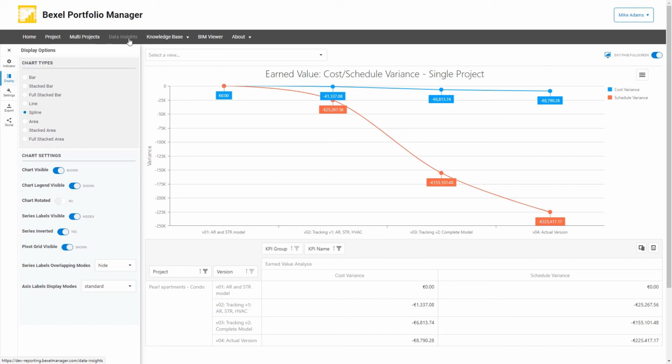The platform will also have additional links and connections with knowledge bases where users can access and use various analysis templates such as IDS templates for automated BIM checks, buildingSMART data dictionary templates for different purposes such as, for example, BIM checks, automated BIM data enrichments, and classifications or similar. Some of the available templates will be predefined and customizable, for example, BIM clash detection matrix, various cost databases, and much more.